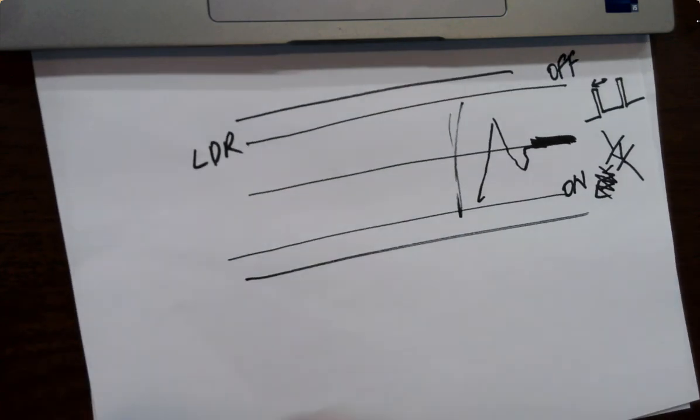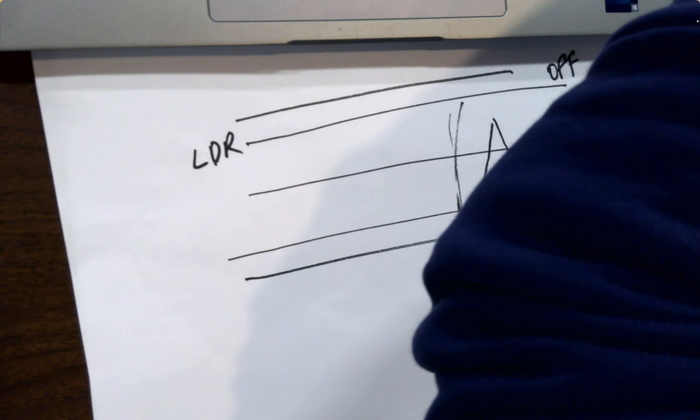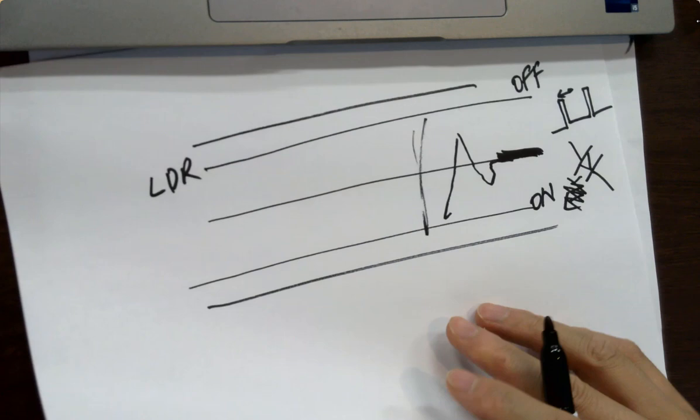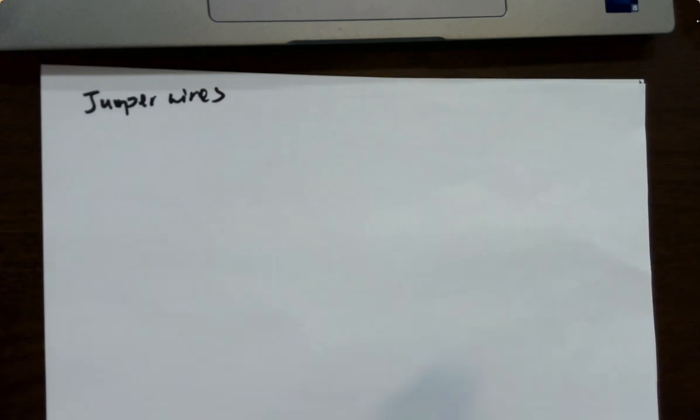What's it when you have a lot of vias on your PCB? Is that fine? You want to reduce the number of vias as much as possible. If you can avoid them, that's okay. You can place parts on the bottom of the board if you want. Then you can reduce the number of vias, so it's easier to route.